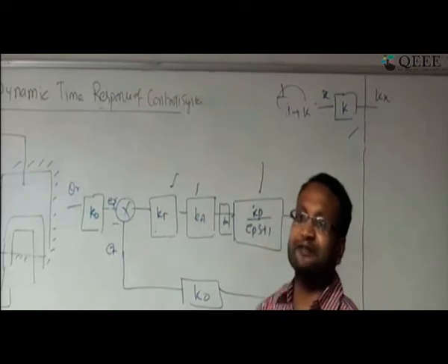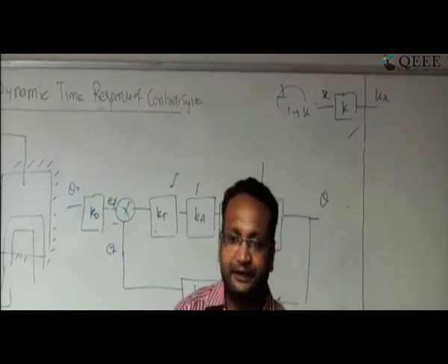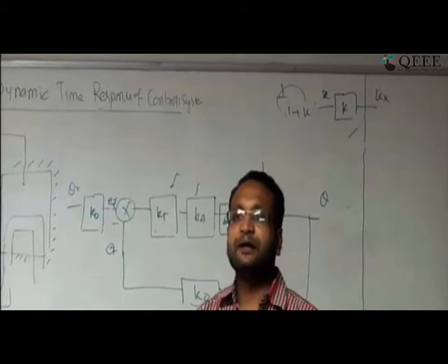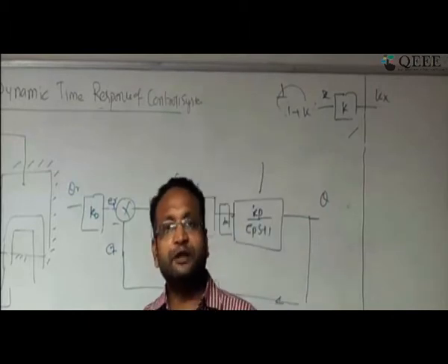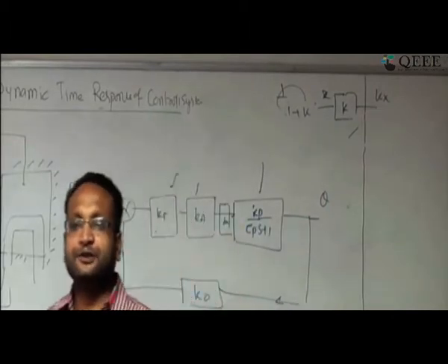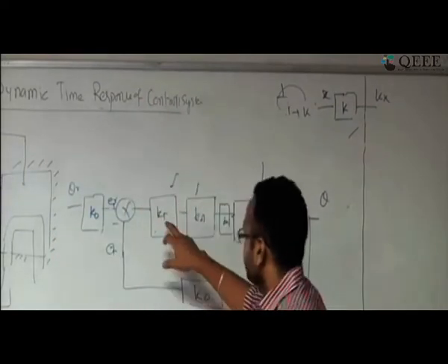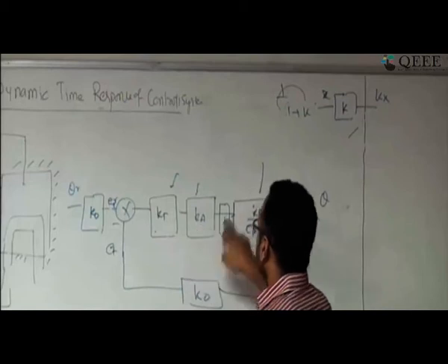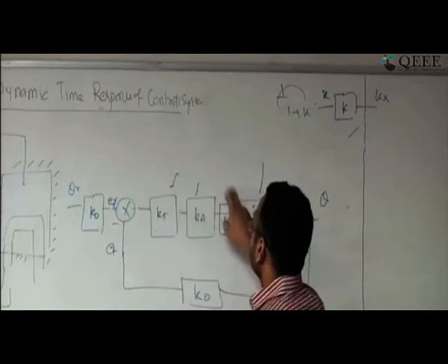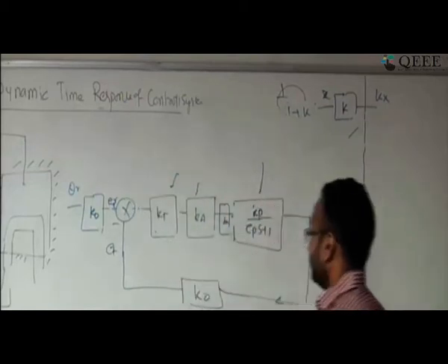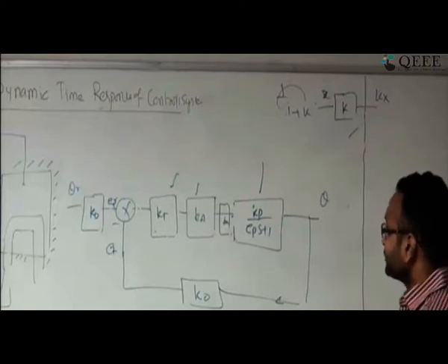That's the meaning of a first order system. It is also called a first lag system. It means there is going to be some delay. A second order system is going to have some more delay. So if you keep on increasing the order of the system, it becomes much slower. Okay. So here I am assuming that the amplifier, transducer, and valve position are all zeroth order systems, and now I am doing the analysis. Okay. So I can think about it.